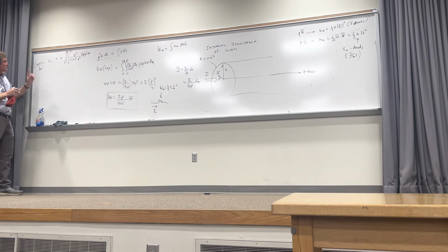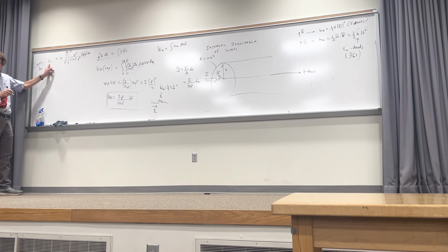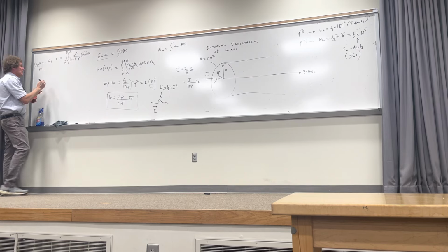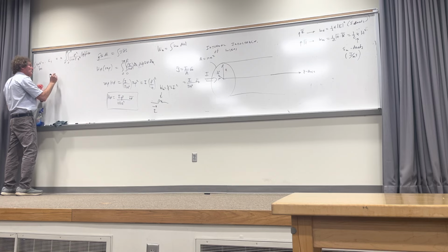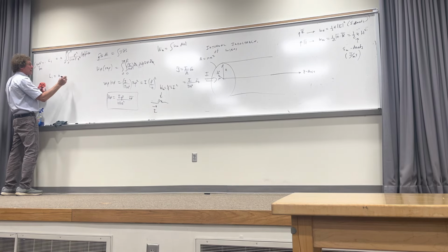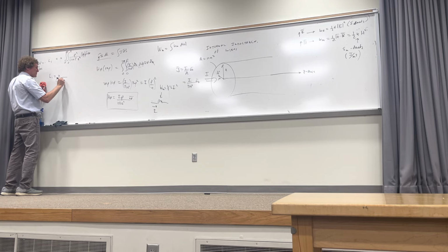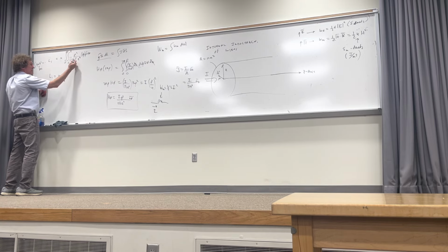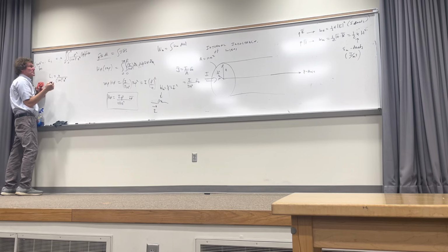Now I've got an equation that is the internal inductance of that wire per meter. Do you see this, class? I'm going to evaluate it in a second. It's not going to be hard either. So now I say that the internal inductance of the wire per meter would be mu, and then I have this business downstairs, so it's 2 pi squared, and this is a to the 4th. Those are all constants. Then I integrate rho squared d rho, which is what?